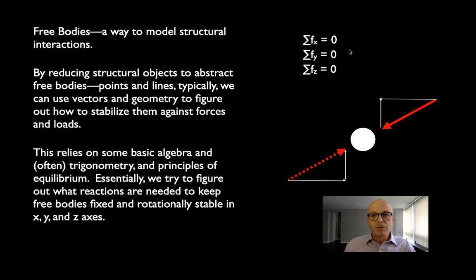Fx is going to be forces in the x direction, horizontal direction. Here, the sum of all forces in the y direction, and here the sum of all forces in the z direction. Now, we'll typically, in our problems, just be doing two-dimensional things, so we can ignore z. We're just going to be looking at forces in the x, horizontal, and the vertical y direction. Later, when we talk about beams, we'll be writing these equations to start out with.